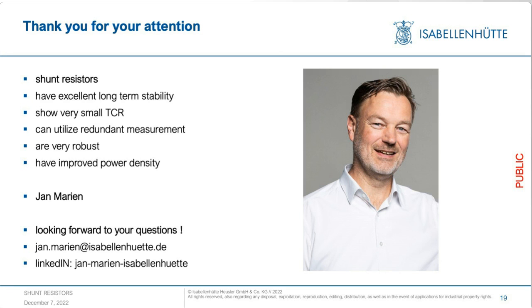So if you do the initial error of the shunt at room temperature and the initial deviation at an elevated temperature, you can put either these two values onto the shunt, or if you're using a mathematical formula to compensate for that, you can even put the coefficients of that formula into that shunt.